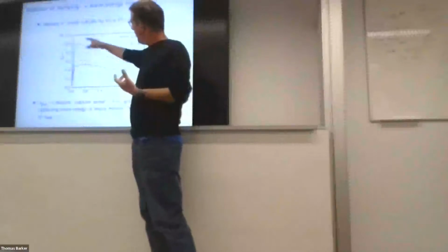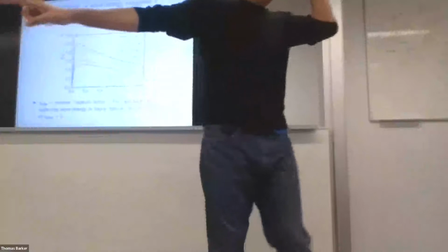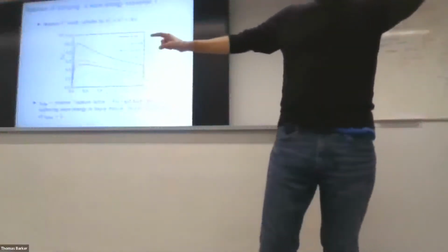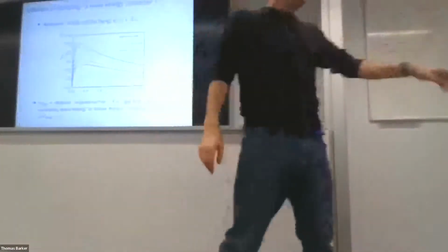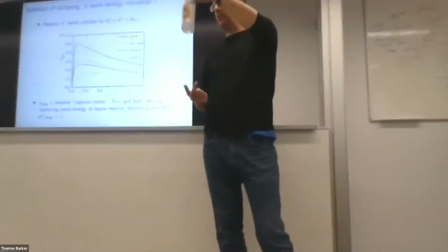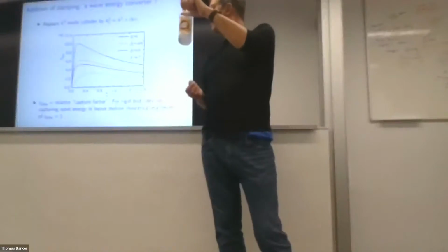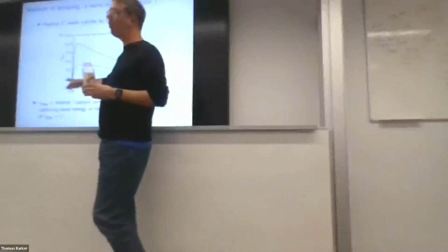These lines show what's called the capture factor, or normalized capture factor, which is a measure of how good that wave energy device would be. Now, with a normal wave energy device, if I take a circular cylinder and attach it to a piston, and it just bobs up and down in the ocean, and I take energy out of that, the maximum energy that I can take out on this scale here is 1.